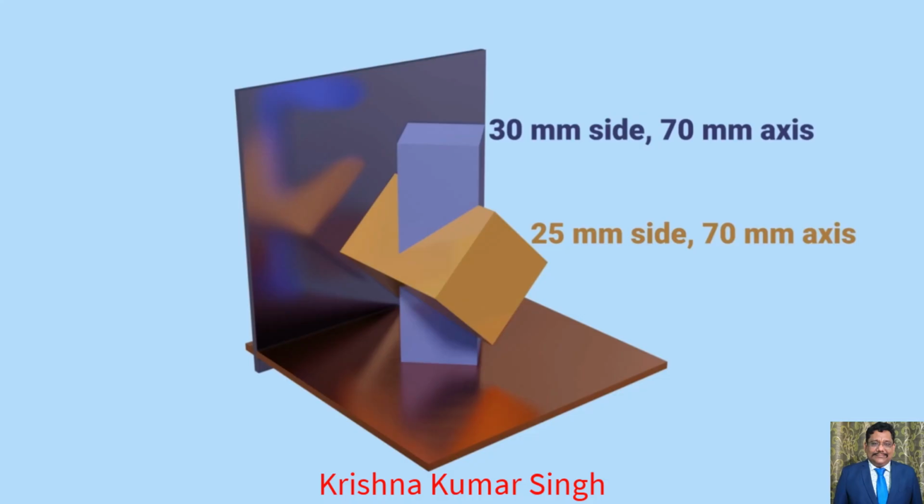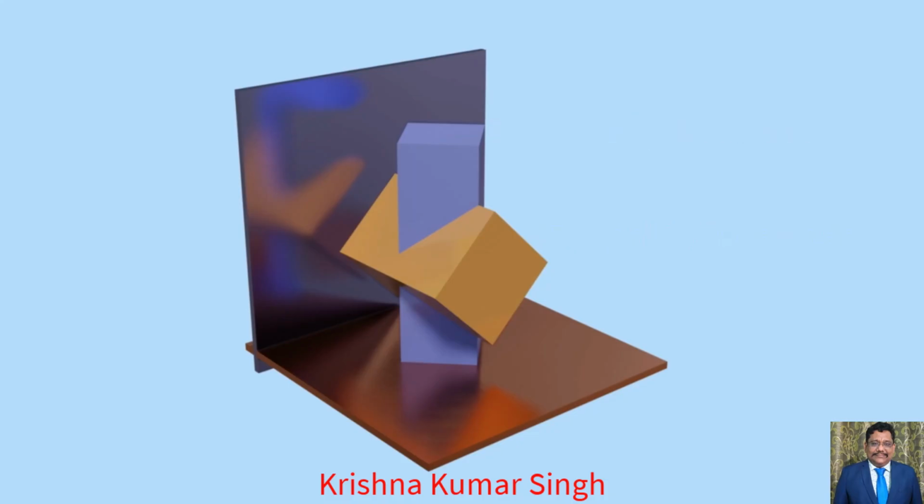The axis of the horizontal prism is parallel to the VP, while the two faces of the prism are equally inclined to the VP. Draw the projection of the solids, showing their line of intersection. In this question, one prism is penetrated by another prism, so to obtain the line of their intersection, we will follow the common steps which we had seen in our previous video.